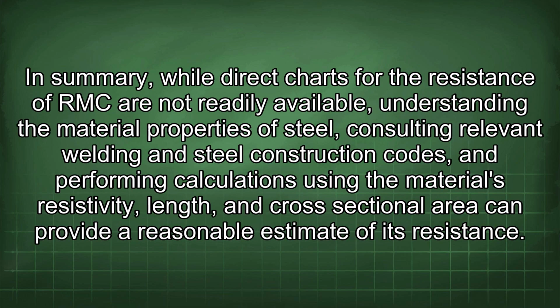In summary, while direct charts for the resistance of RMC are not readily available, understanding the material properties of steel, consulting relevant welding and steel construction codes, and performing calculations using the material's resistivity, length, and cross-sectional area can provide a reasonable estimate of its resistance.